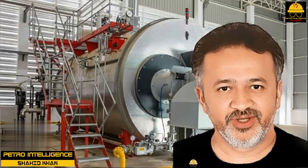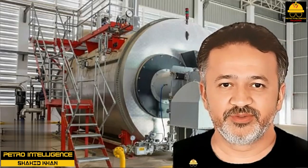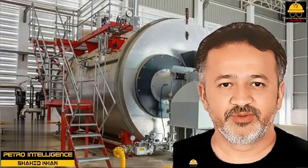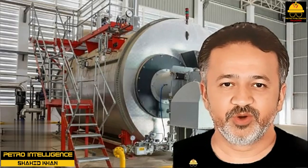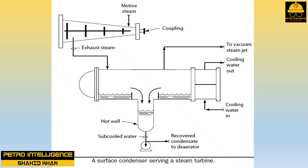The surface condenser is an improvement on the barometric condenser because it permits recovery of clean steam condensate. Other than this factor, the old-fashioned barometric condenser is more efficient than the more modern surface condenser. This picture shows the type of surface condenser most widely used on older steam turbines. Note that it has both a vapor and a liquid outlet.